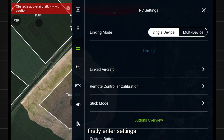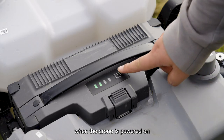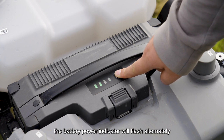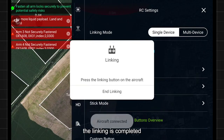Firstly, enter Settings. Enter the remote controller interface. Click Link. Then the remote controller will prompt DJI voice. When the drone is powered on, press and hold the battery power button for 5 seconds. The battery power indicator will flash alternately. When the remote controller beeps twice, the linking is completed.